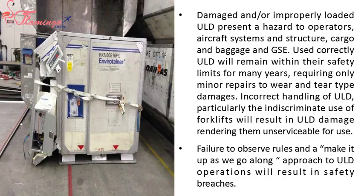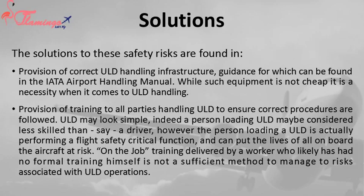Used correctly, ULD will remain within their safety limits for many years, requiring only minor repairs to wear and tear type damages. Incorrect handling of ULD, particularly the indiscriminate use of forklifts, will result in ULD damage, rendering them unserviceable for use. Failure to observe rules and a make-it-up-as-we-go-along approach to ULD operations will result in safety breaches. The solutions to these safety risks are found in provision of correct ULD handling infrastructure, guidance for which can be found in the IATA Airport Handling Manual.